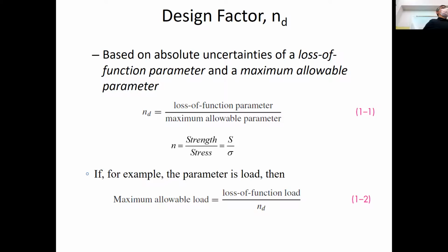So I heard the 3 here. 3 is not untypical for some civil structures. They can afford the weight, and yes, if you're designing a dam, I mean, we are hearing about hurricanes these days, and we hope everything goes well. You want to use a 3. But if I'm designing an aircraft, there is no way I want to get close to the 3 because of the weight issues, right? Even within the aircraft, I can be using 1.2 for certain components, but 1.5 for more critical components. So really, it depends.